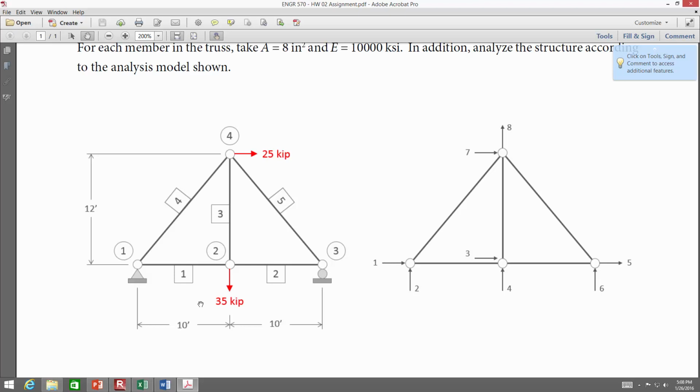For this joint, the horizontal displacement is degree of freedom 7. That way we're all agreeing on the same thing. So for this truss, we have 5 members that we must assemble. Each of them has a 4 by 4 stiffness matrix. We must assemble each of those 5 members to achieve an 8 by 8 for the whole system. Everybody okay with that?